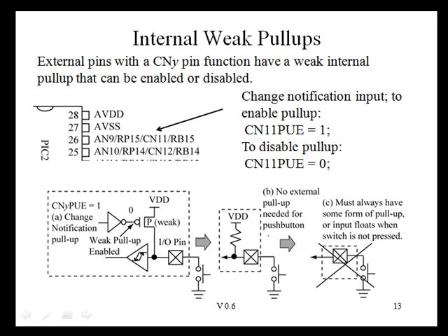The previous slide mentioned that when using a push button switch, we needed an external pull-up so that when the push button was not pressed, the pull-up was pulling the floating input up to VDD. It turns out that it's a pain to have to wire up that external pull-up resistor, and since push button inputs are common for microcontrollers, the PIC24 designers designed each port to have an internal pull-up that can be enabled by a bit in a special function register.